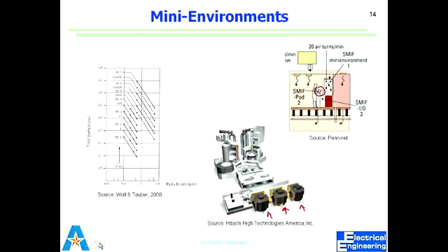So this is on the clean room. It's particle size and the total particles per cubic meter that defines class 1, class 10, class 100, class 10,000. So it's not just how many particles, it's the size of particles. If we push down to the smaller particles, we are a little bit relaxed on how many particles can be allowed, right?